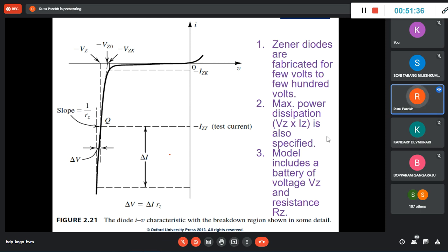So this curve you are very much aware of. Now we are targeting Zener, and as you can see here, this is the reverse, and this line, you know, it has a slope. It is slanting. It's not a straight line, although, as I said, an ideal line is a straight line, but we don't get anything ideal. This is a practical one. It has a little slope, and this slope shows the resistance. Now you are understanding, right? And there is a resistance involved.